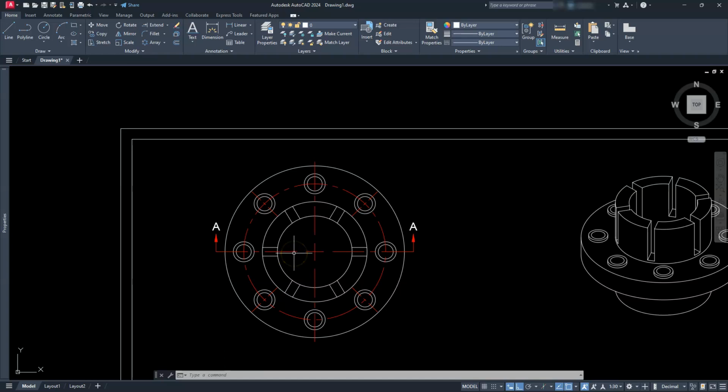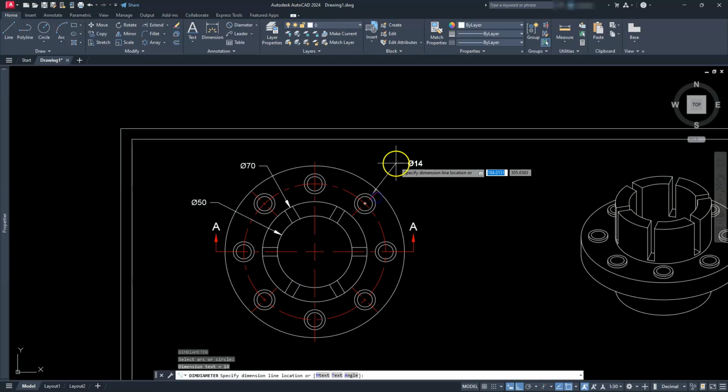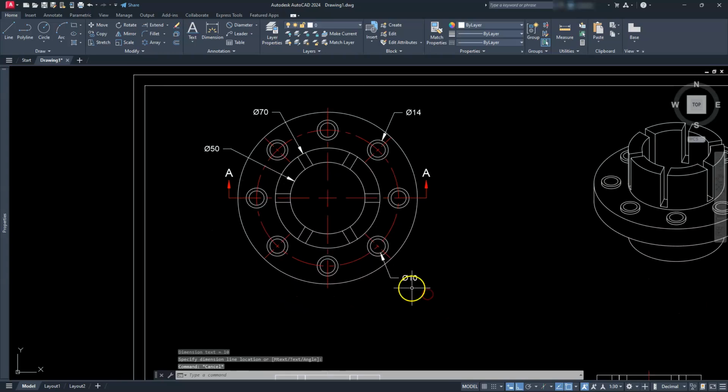Let's go ahead and put the rest of our dimensions onto this. So I'm going to knock out my diameter dimensions first, right? I can either switch over to the annotation tab, or I can use all of the ones that are located here. Either way is fine with me. I'm just going to use a diameter here. And I'm going to do this a quicker way, just by selecting here. Just hit enter on your keyboard to go back. Select here. Go ahead and hit enter. Select this one. Enter one more time. And let's place it on here. Yep, that looks good. Go ahead and hit escape.